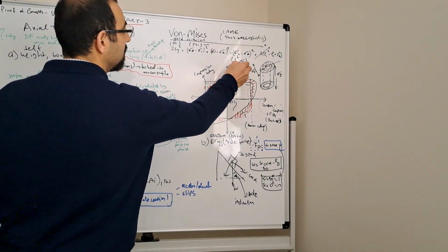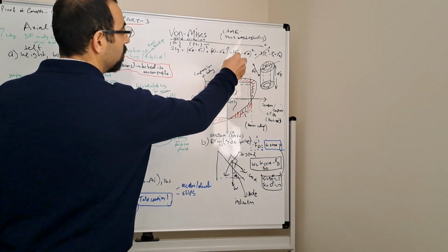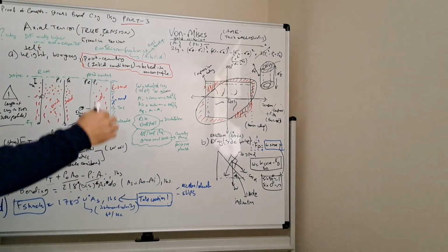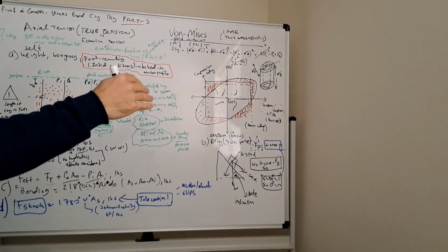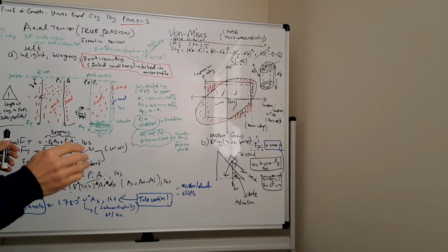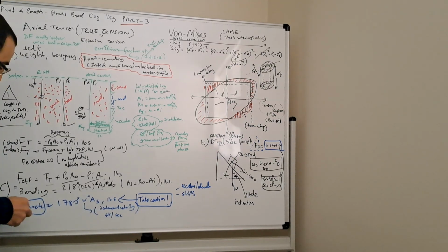So that's why there's a question mark of plus and minus to the tension. It's maximum at the outside, I think, and the minimum on the inner wall. So you can calculate the equivalent von Mises stress on both walls. So the other one is the shock load, right?